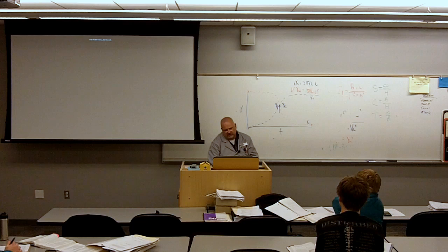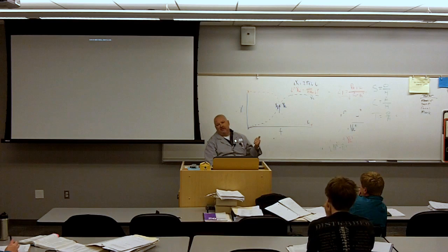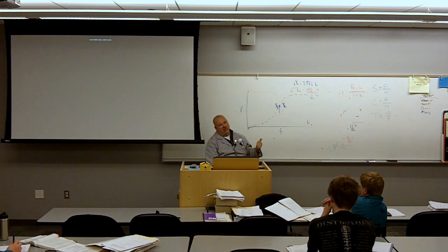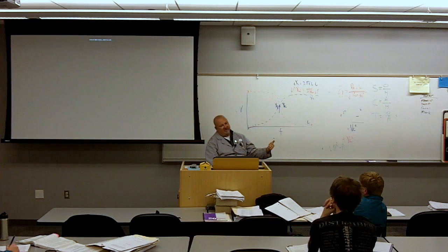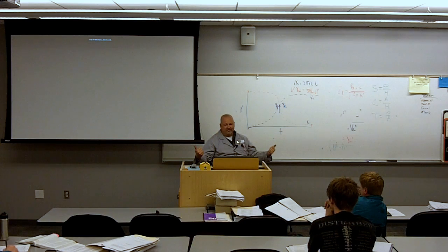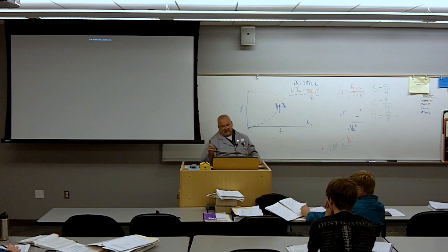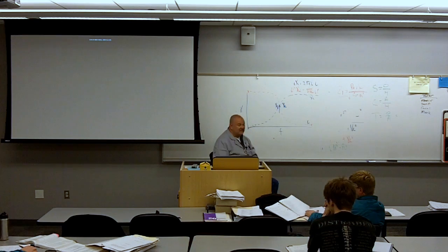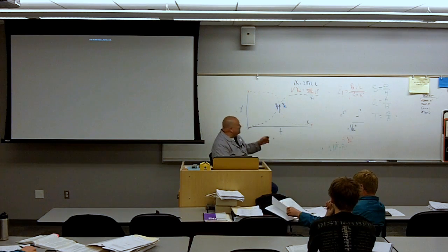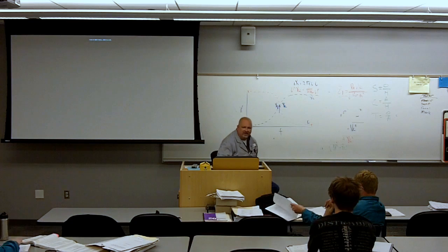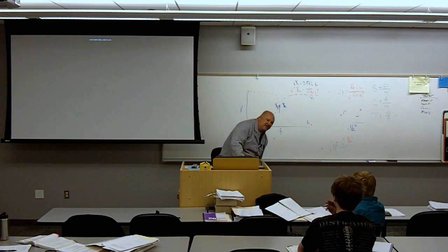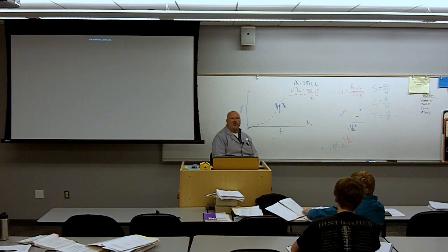Anybody have any questions on anything we discussed in this chapter? There's a lot going on in this chapter, but really this chapter is nothing more than X sub L equals 2 pi FL, X sub C equals 1 over 2 pi FC. When they're equal to each other, you're at resonance. Check this out. If I have a series circuit that contains a resistor, an inductor, and a capacitor, and I am below resonant frequency, what kind of a circuit am I dealing with?